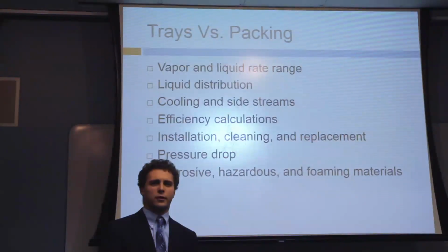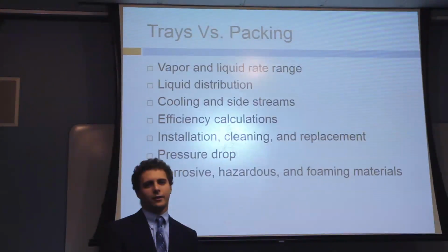Pressure drop can be important in certain situations, especially with vacuum distillation. Packed columns have much lower pressure drops in general than tray columns, which makes packed columns a wiser choice for vacuum distillation.